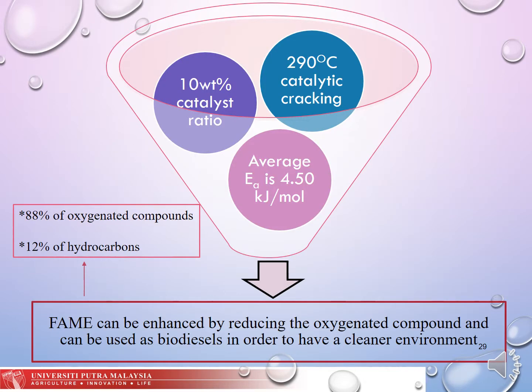Okay, to conclude, I would say that 290 degrees Celsius and 10 weight percent of catalyst ratio is the best condition to conduct the catalytic cracking in order to achieve less oxygenated compound in the oil. Therefore, the average activation energy was just 4.50 kilojoule per mole, so there is no external energy needed to initiate the process.